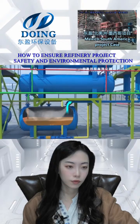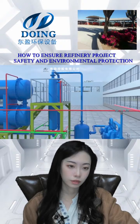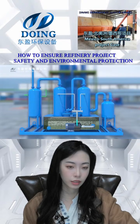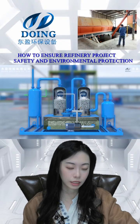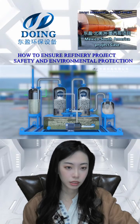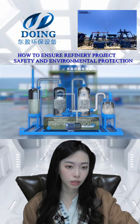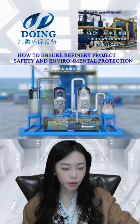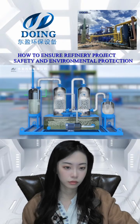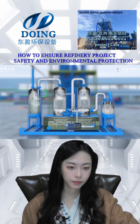And for the feeding material, there are some differences. For the batch type one, we don't need pre-processing. A whole tire we can put in directly, and the plastic we can just dry first and put inside the reactor. But for the continuous one, you need some pre-processing, crushing it into rubber powder and plastic particles. Then we can ensure it feeds in at a sealed environment, so there is no gas release.